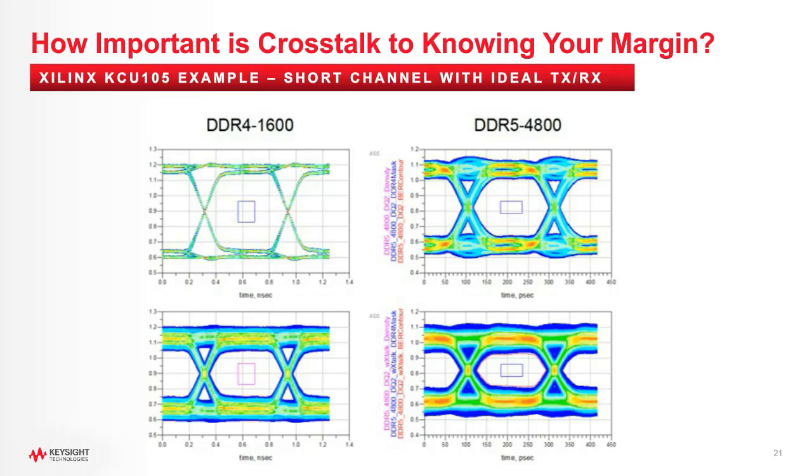So, for instance, if I don't put in any numbers for random jitter or deterministic jitter, then I can simulate jitter-free. Likewise, when it comes to crosstalk, if I don't put in any of the crosstalk neighbors, if I just simulate without them, then we don't see the impact of crosstalk.